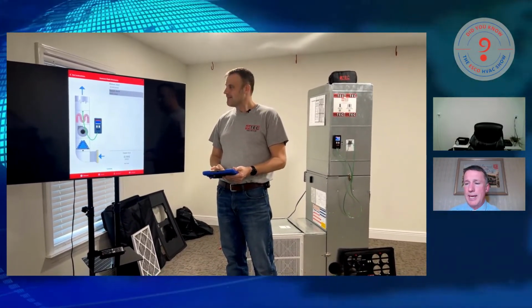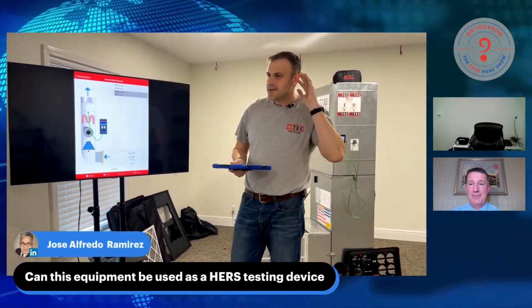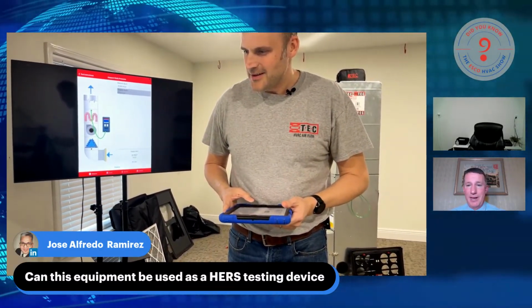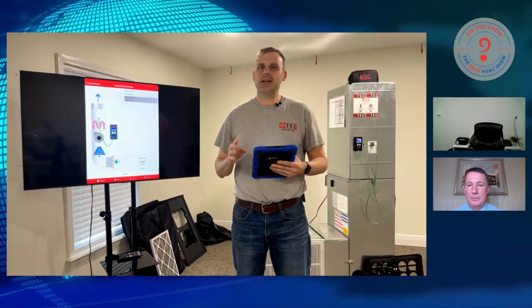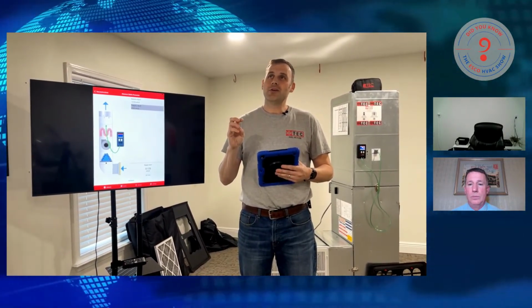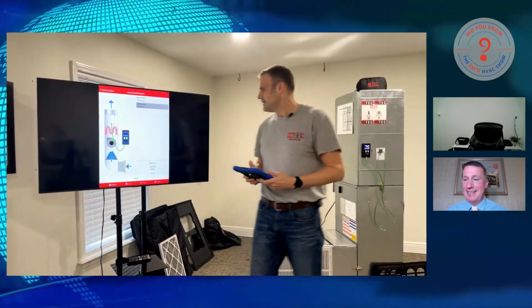You know, Chris, one of the questions that came in from Jose was, can the equipment be used as a HERS testing device? Say that one more time. So the question came in, can the equipment be used as a HERS testing device for HERS ratings? Yes. So I don't know all their rules, but here's what I'll tell you. Standard 310 allows for 4 methods to measure airflow, and they are pressure matching. You can use TESP, which is static pressure mapping. You can use a flow hood, and you can use a Trueflow Grid. That's your 4 methods you can choose from if you're executing a standard 310 test. Awesome. Fantastic. Thank you.